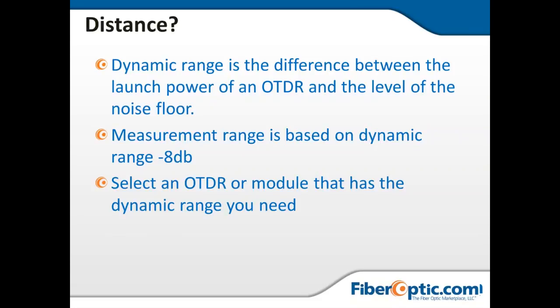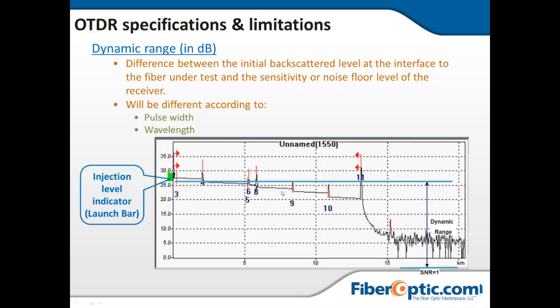One of the other things that we could do here is instead of measuring at 1310, we can measure at 1550. If we measure at 1550, we have about a 0.22 dB per kilometer loss. So if we were to measure the same 100-kilometer span at 0.22, that's only going to absorb about 22 dB of power over that length. If we add the 8 dB of overhead, we're really only needing about a 30 dB OTDR, which is a very, very comfortable range. Typically we're not even going to sell OTDRs that come in below like 34, 32 nowadays.